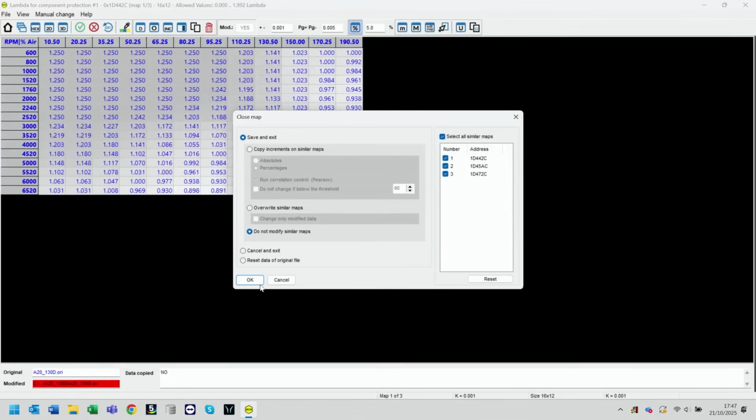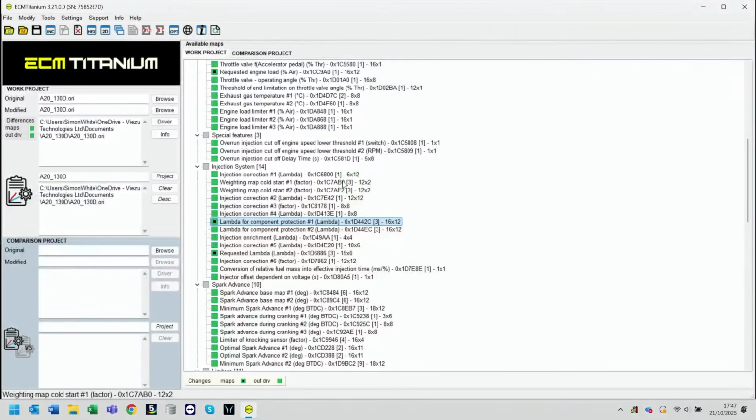And you're going to be chasing the tune, and importantly, you're going to start making overcorrections into other maps to try and desperately get that number on the dyno to make the customer happy. And then you start making changes to maps that don't need to be touched. Start adding more fuel, adding more boost pressure, and still you're not going to get there. You're just fighting the strategy within the ECU at that point, and all you're doing is actually almost making the situation a little bit worse. So there are two main maps in our injection system.